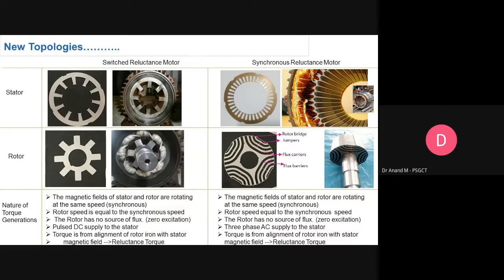The main advantage, as you could see from here, is that the reluctance drive can be either a switched reluctance drive or a synchronous reluctance drive. The stator is almost, not exactly, similar with respect to the induction and PMC drive system. In the rotor, we can think about the absence of magnets, copper windings, copper bars, commutators, end rings, aluminum bars, etc., which will have a very high influence on the rotor inertia.